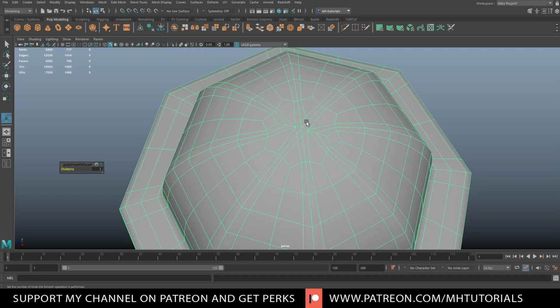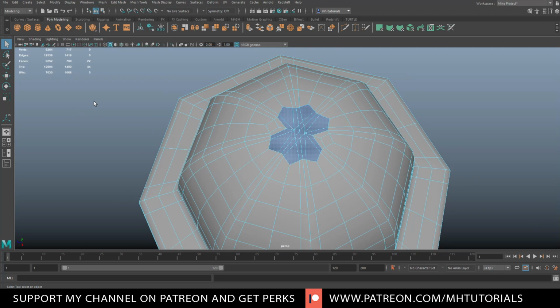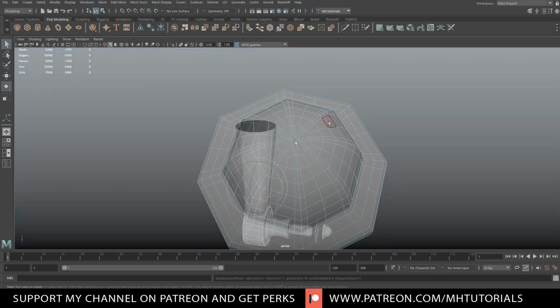What you could do is go in here, go into face, basically select this area right here, and then oops, go back 1, increase that selection. So basically you got this selected, cut that out, and then take the multi-cut tool and connect it up again. So fill hole and do that. But we don't need to because we don't have any n-gons. This is not going to be deformed. It's not going to be animated, so it's okay, right? All right.